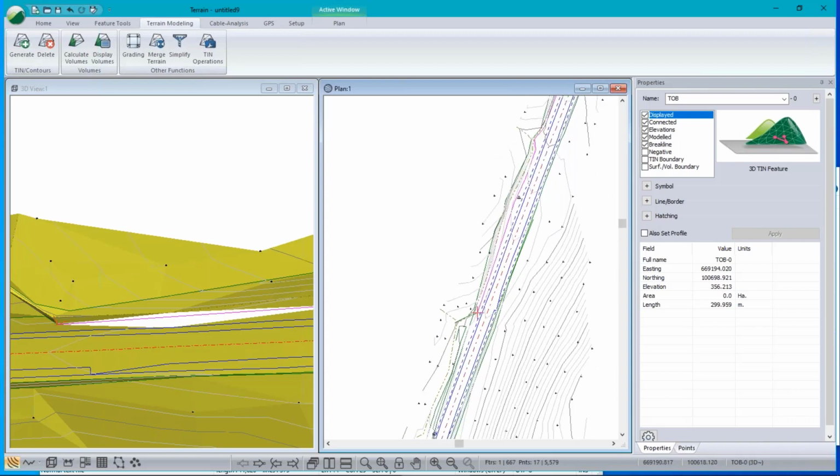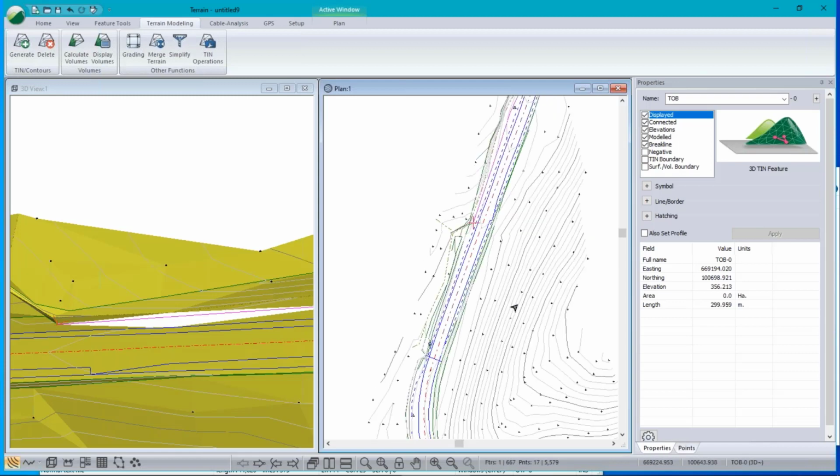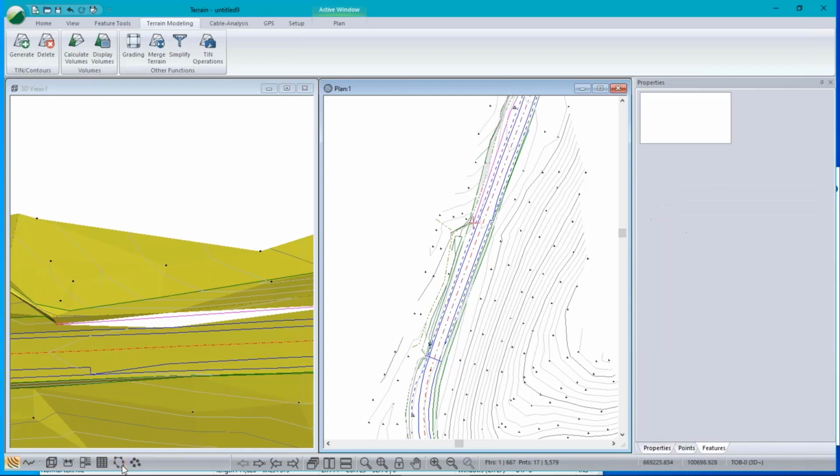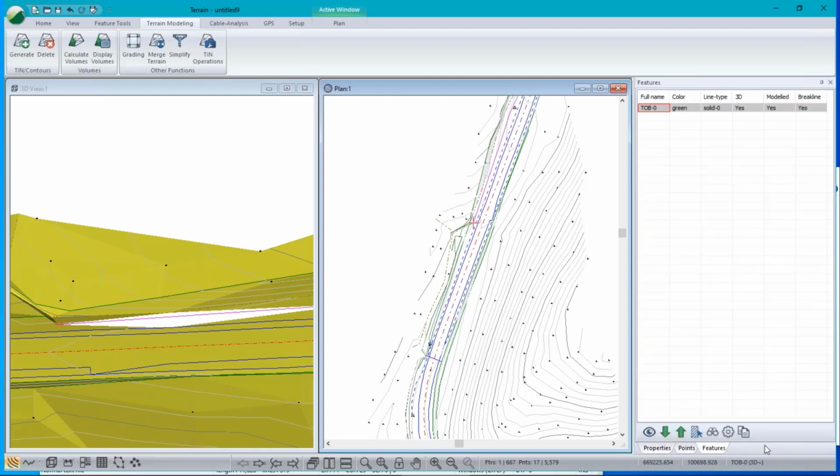For example, ditch lines that are crossing, you might have a section of road with ditch, and then the road goes into fill and there's no ditch, and then a kilometer down the road, you're back into ditch. If those two ditches are connected, you're gonna have a break line segment that is huge. It's gonna be a kilometer long. So there's a tool for that. I don't really have time to cover much here, but let me just summarize quickly.